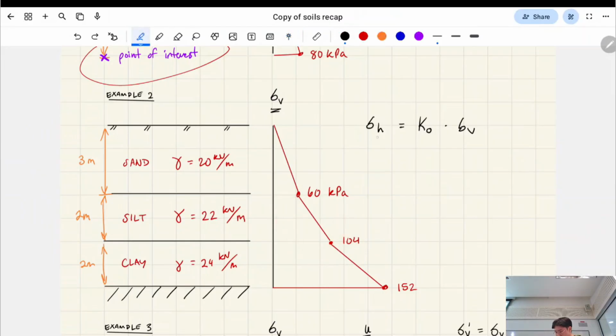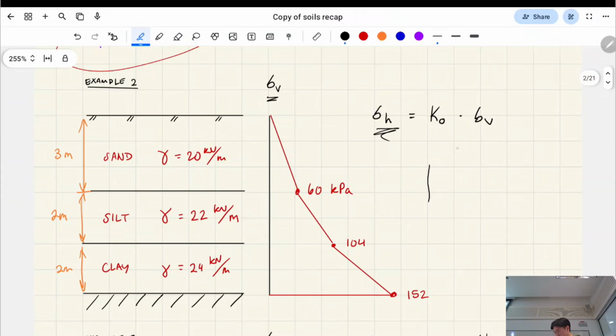Okay, the other thing to keep in mind is soil expresses stresses in different directions, and we usually care about vertical and horizontal stresses. Vertical, because we step on soil vertically, so it gets vertically compressed. Horizontally, you'll find out in geotech, which is the next course after this, in term 1. You'll have retaining walls and stuff like that, and it's very important to understand horizontal pressure, because that's what's going to cause sliding and overturning on that retaining wall. So soil can also cause this horizontal pressure.